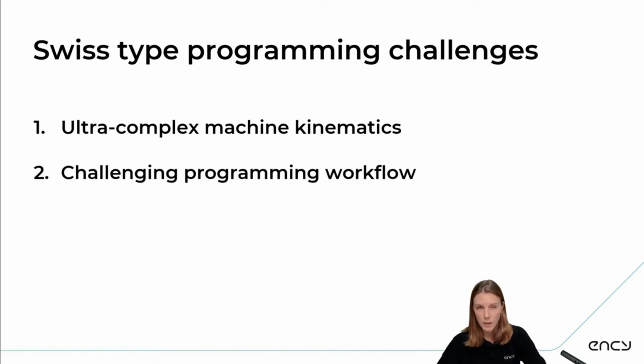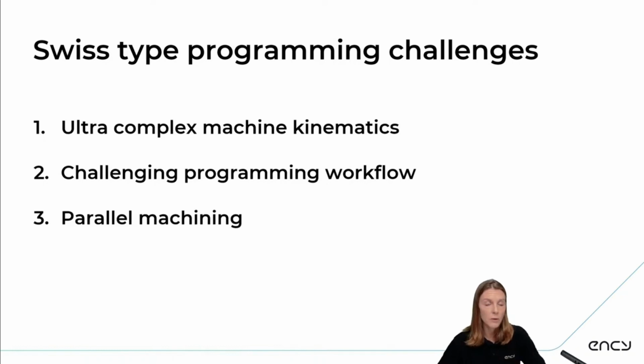That's quite a challenging workflow because besides the cutting operations or cutting strategies, we need to be aware of additional operations for Swiss lathe like pickups or sub-spindle working. And we need to have parallel machining in our mind, so we need to be aware how each of the channels work together. That's not an easy task.